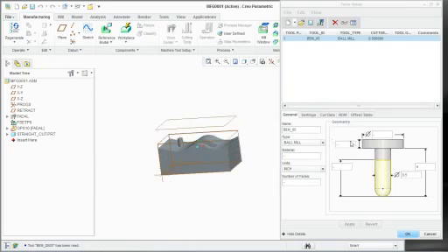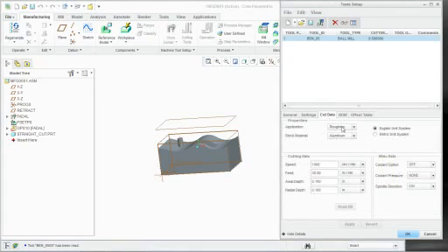Okay. Now, this stuff is pretty straightforward. Essentially, you have just an edited tool that has a standard shape, and you change the shape for it. But what I find is a lot of customers don't fill out this information right here in the cut data. And so what this allows me to do is regulate speed, feed, depth of cut, and step over based off of a material and an application. And then what I can do is fill this information out based on these two ideas and the tool, put in my cut data, and then save that to that .xml.